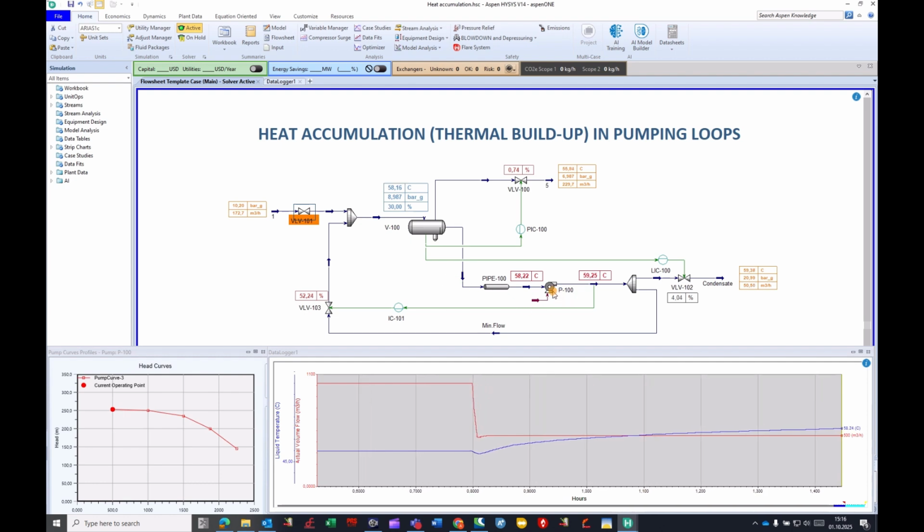So the best move in this situation is to revamp the pump to make the rating point a much lower flow and eliminate or reduce the mean flow recirculation. This is the typical and classic way of coping with that situation.